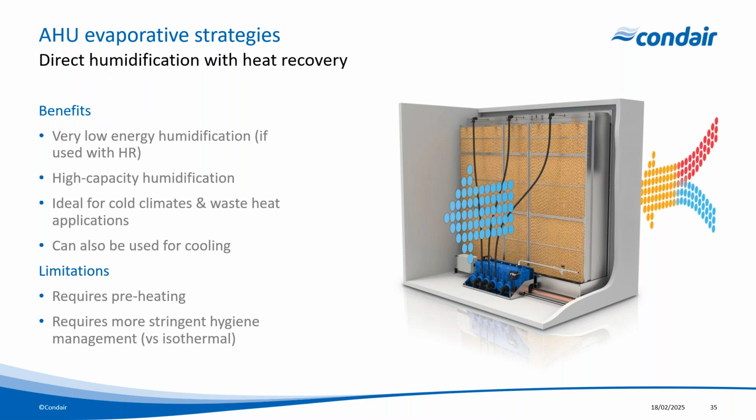In terms of limitations, there are, of course, a few here that we do need to talk about. You may not need that cooling effect. If you're looking for humidification, but you don't need the cooling, one of the things you need to consider is the potential need to preheat the air in order to offset that cooling effect that we get with the evaporation of the water. So of course, really ideal if you've got an application where you need humidification and cooling at the same time with waste heat available. If you don't have that waste heat available and you don't need the cooling, you would potentially need to look at preheating that air before it goes through the evaporative cooler.